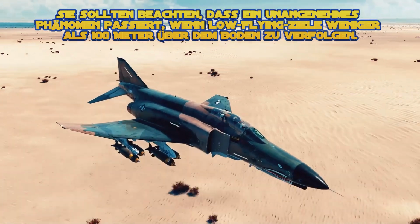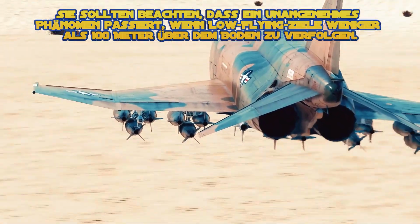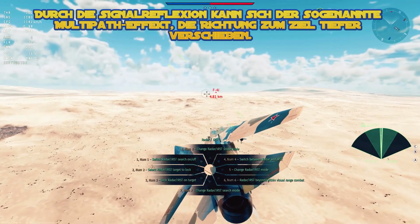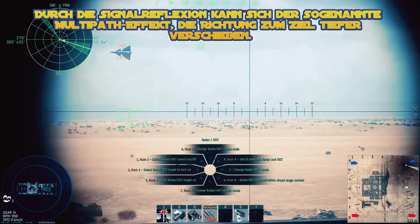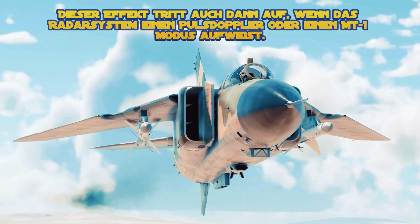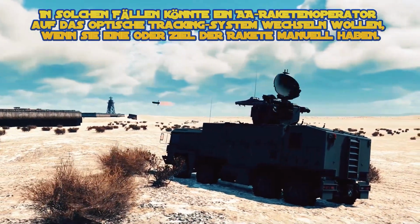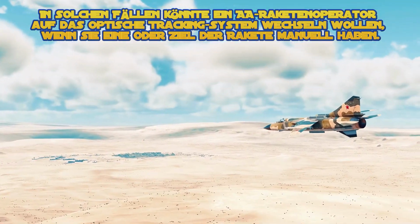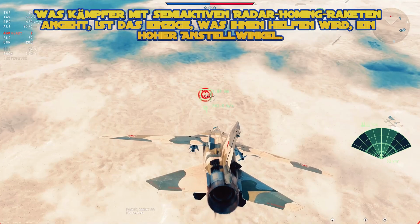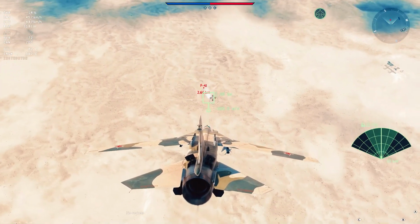You should keep in mind an unpleasant phenomenon happening when tracking low-flying targets less than 100 meters above the ground. Due to signal reflection, the so-called multipath effect, the direction to the target may shift lower. This effect appears even when the radar system has a pulse Doppler or an MTI mode. In such cases, an AA missile operator might want to switch to the optical tracking system if they have one, or target the missile manually. As for fighters with semi-active radar homing missiles, the only thing that'll help them is a high angle of attack.